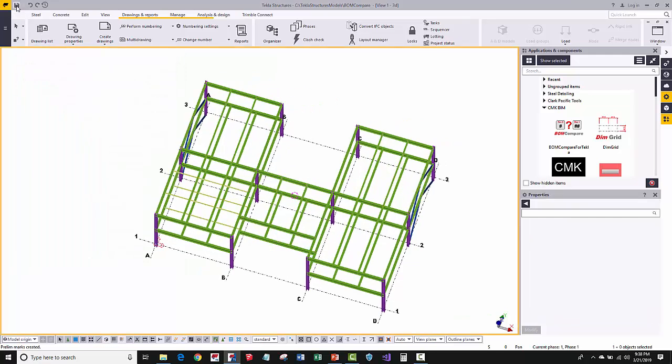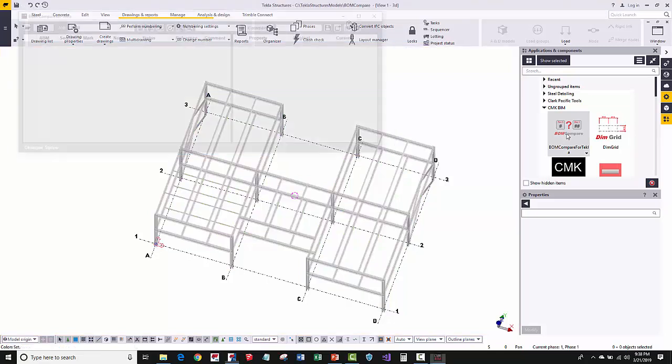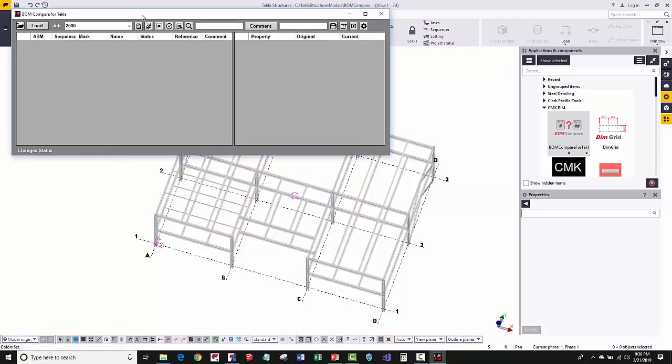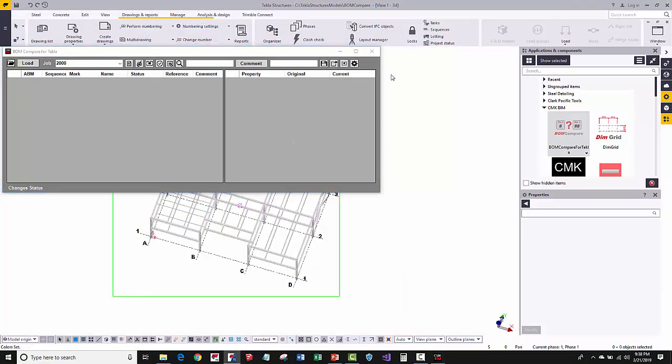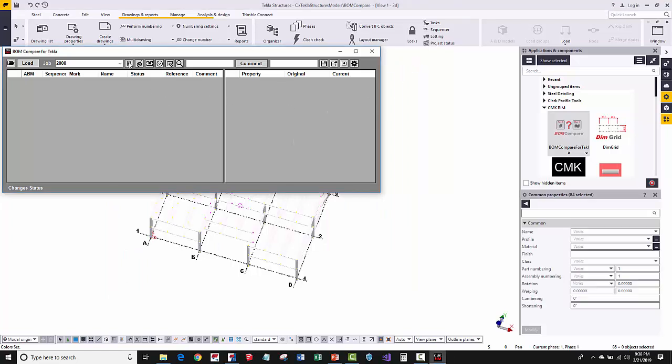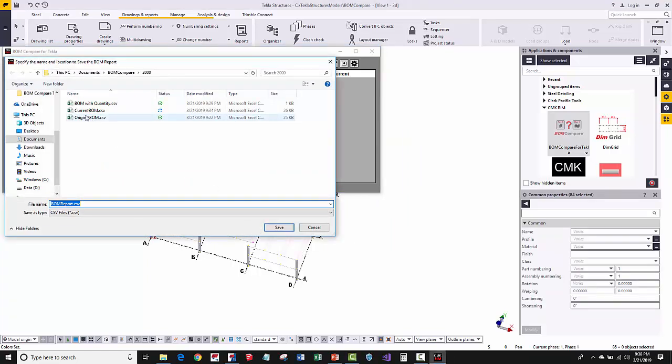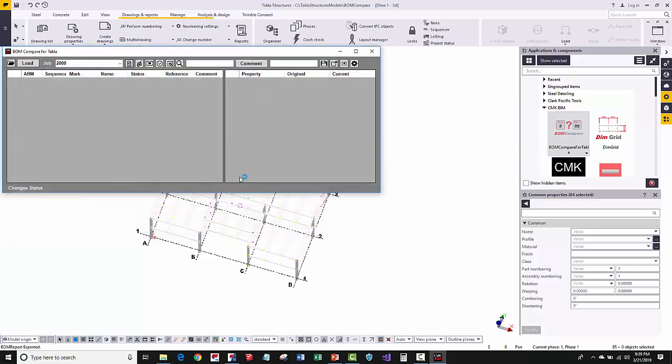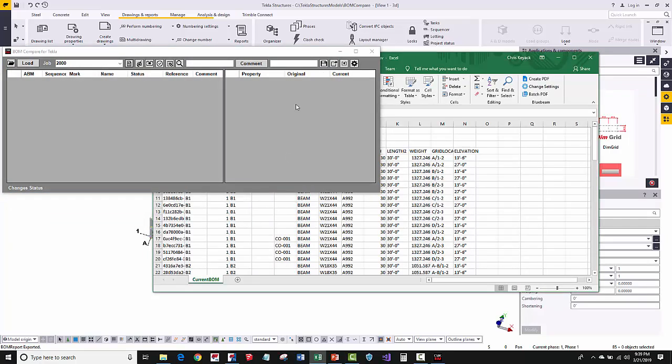All right, so let's go ahead and save that, and then let's export the updated bill of material. So we've got the tool that's now open. We're going to select all of the objects, and then we're going to run the export. I'm just going to say export this as the current bill of material. You can call this Rev 1 or Rev 2, whatever it is, or even tie it to a change order, whatever makes sense based on your fabricator standards for communicating the file. So I'm just going to go ahead and save this. And then now we've got that exported.